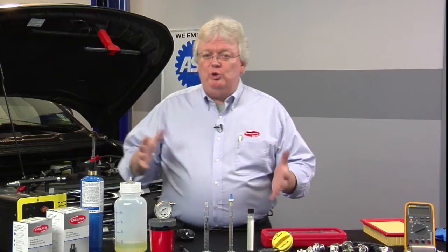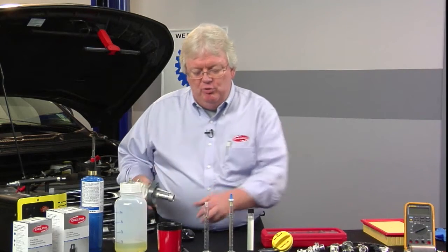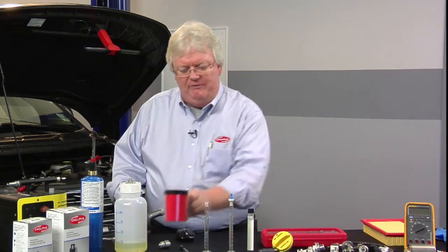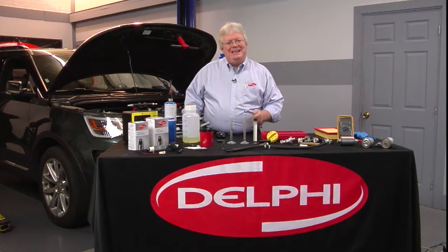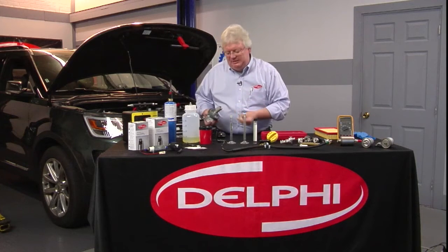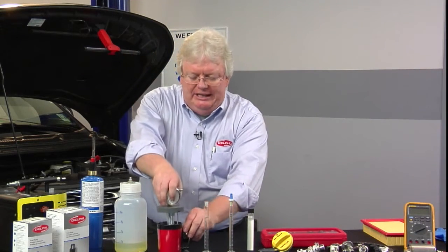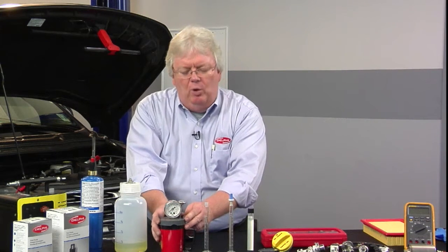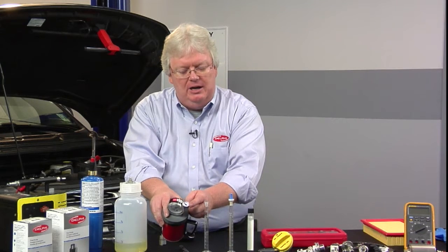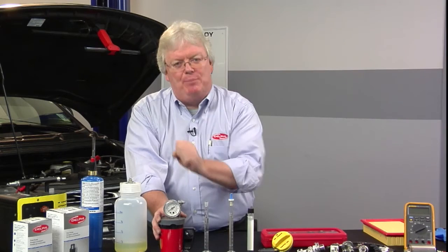So some of the tools from yesteryear, like this Reid vapor pressure test kit, where you literally take a cup of water and put this coffee cup in the microwave, heat it till it boils, and then you get a sample of gasoline from an approved container, put it in this little receptacle right here, and when this goes into the hot water, you watch for the temperature to come back to 100 degrees Fahrenheit. And at 100 Fahrenheit, whatever that pressure is, that's called the Reid vapor pressure.